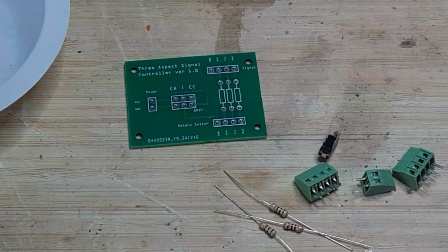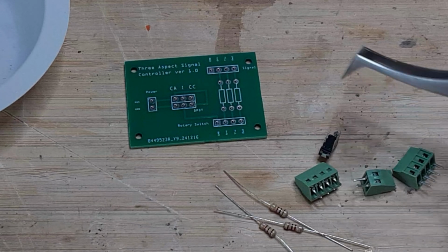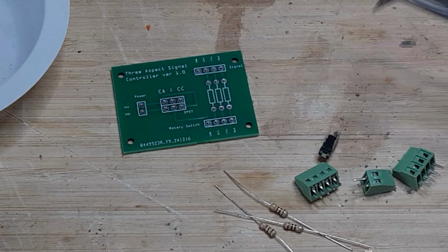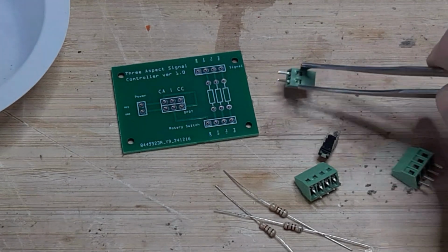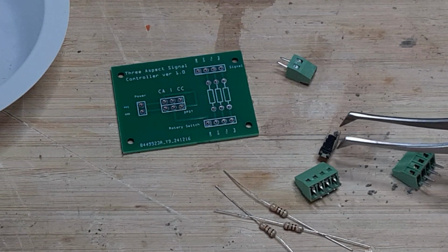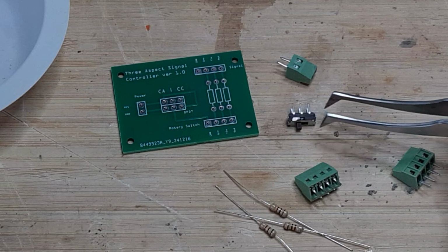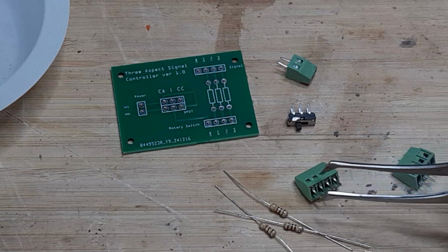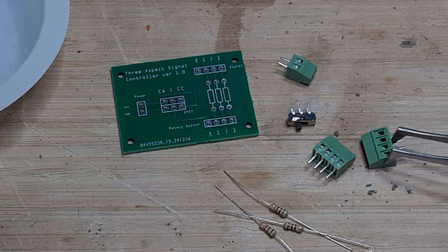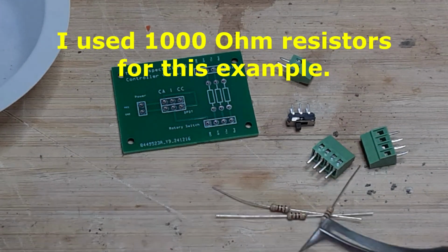Here are the parts you need to build the circuit board. First, this printed circuit board. I bought 10 of these boards for just over $7, including shipping. Second, a 2-pin screw header block for DC power. Third, a DPDT switch to select common anode or common cathode wiring. Fourth, two 4-pin header blocks, one for the signal and one for the rotary switch connection. Finally, you'll need 3 resistors matched to the LEDs in the signal.